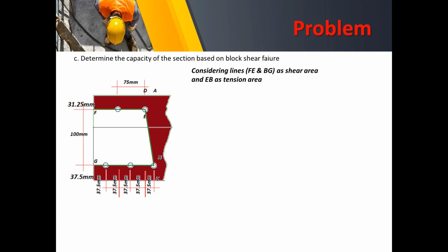And that parallel area is actually the shear area, while EB is the length perpendicular to our loading. Only that it is inclined because of the staggered connection. Hence, note here that there will be a pitch and a gauge distance. Now, computing for the shear area first.